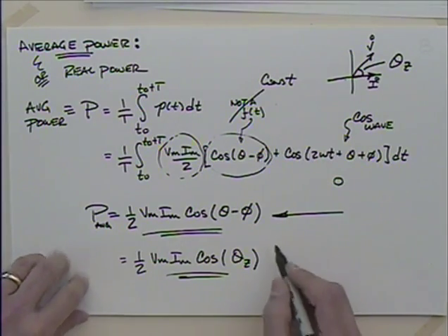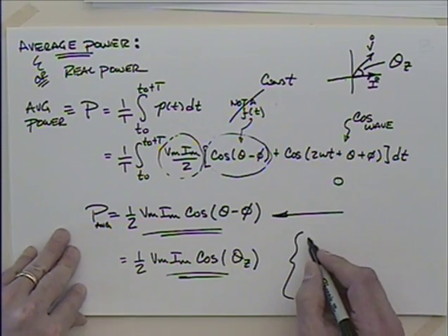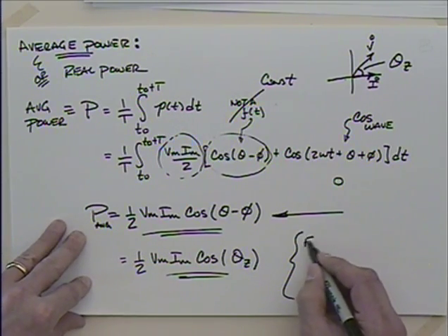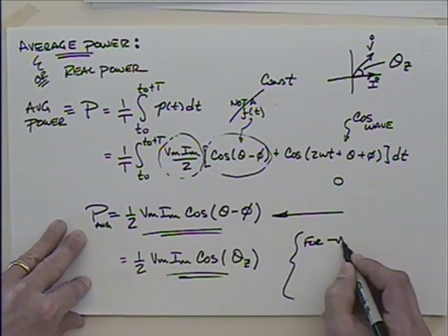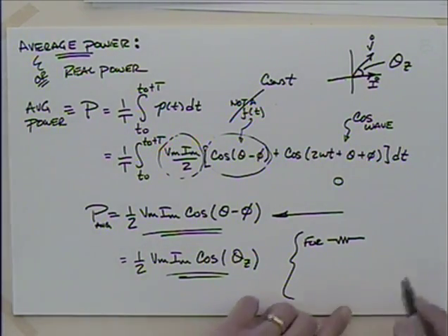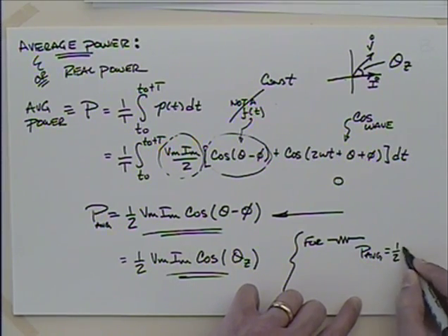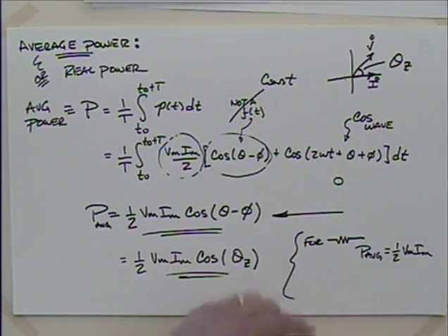So there's implications of this. If I have a resistor, so for a resistor, what is this power equal to? Average power is going to be equal to 1/2 Vm Im, isn't it? And you might say, well, I'd expect it to be Vm times Im. Where did that 1/2 come from? That's because we've cluttered things up with RMS and whatnot, and we will soon talk about that next week.